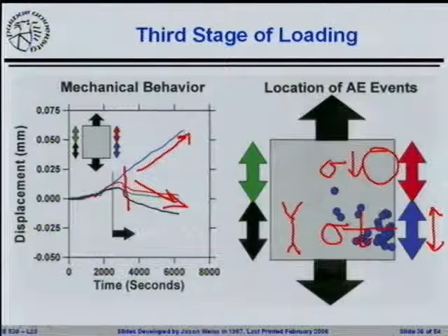Okay. So are you then saying that you could never get compression out of that portion of the testing material? Well, this is a direct tension test. And what happens in this particular one is once this crack starts to form, you no longer have just pure uniaxial tension. You've got a crack forming on one side, and you're starting to bend the sample a little bit. So it's likely you could have a little bit of compression on the one face. But if you were just pulling it in tension, everything would stay in tension, but you'd still have unloading.